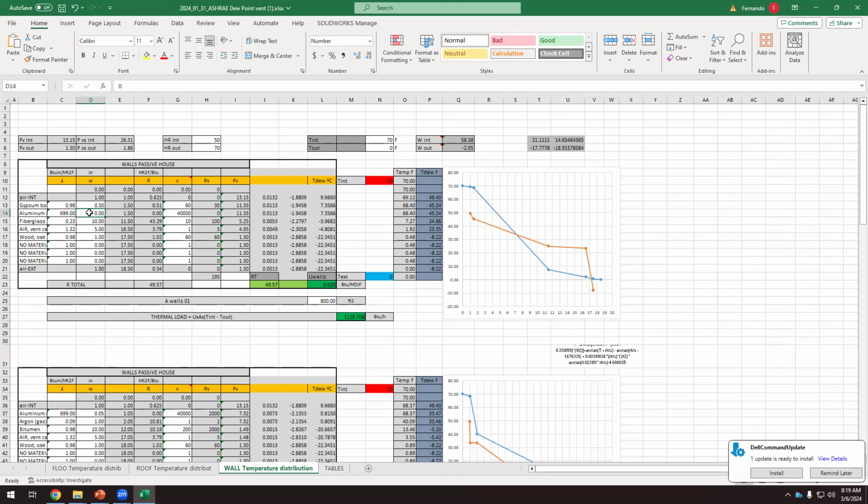And it has to be something. The key point is this value, the vapor resistivity. The vapor resistivity of this aluminum foil is 40,000. That's the tape that they apply to the OSB board. We saw that in Benson wood.